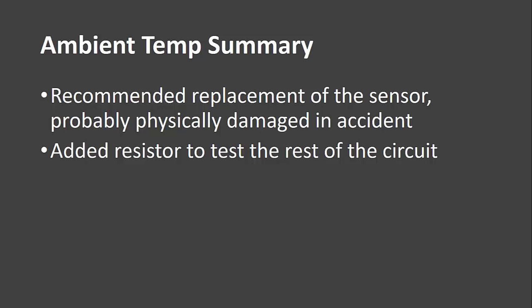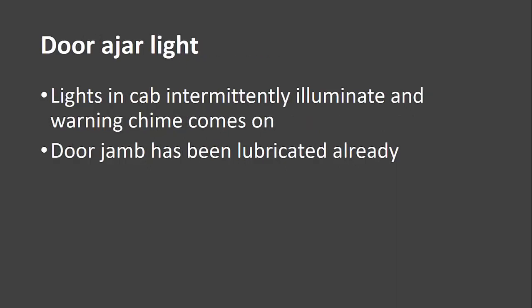So, resistance substitution for temp sensors is a great way to test the rest of the circuit, but it's also a great way if we need to get a monitor to run or a test to run. We can kind of trick the computer.